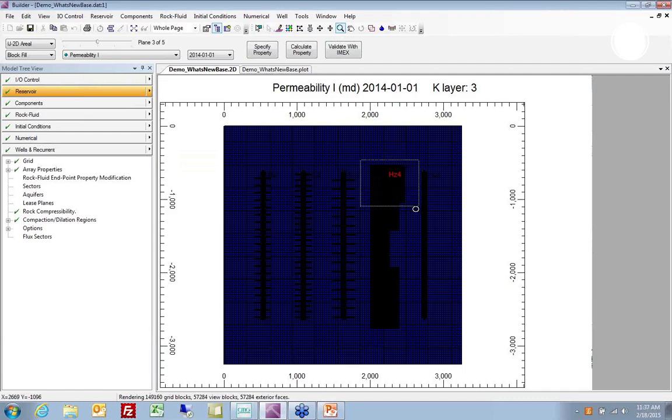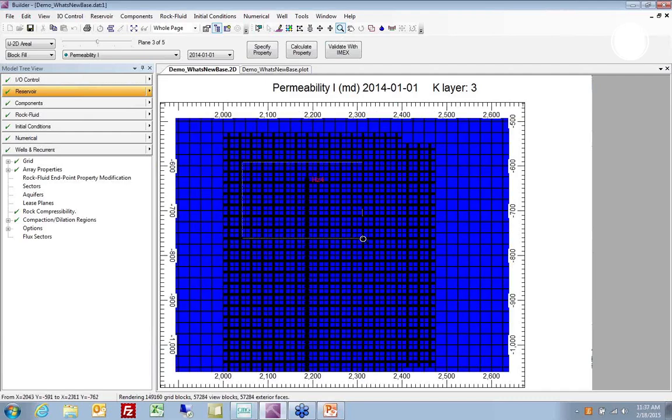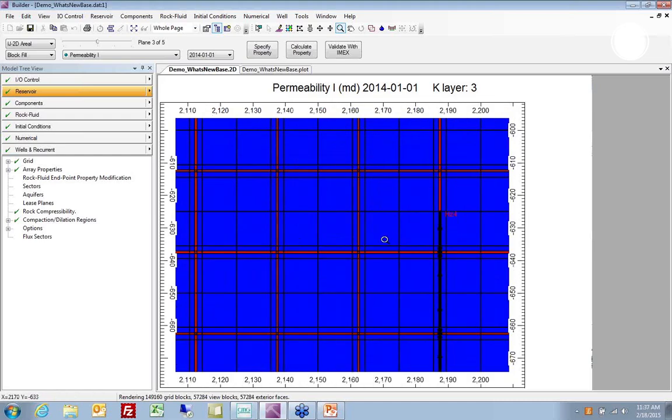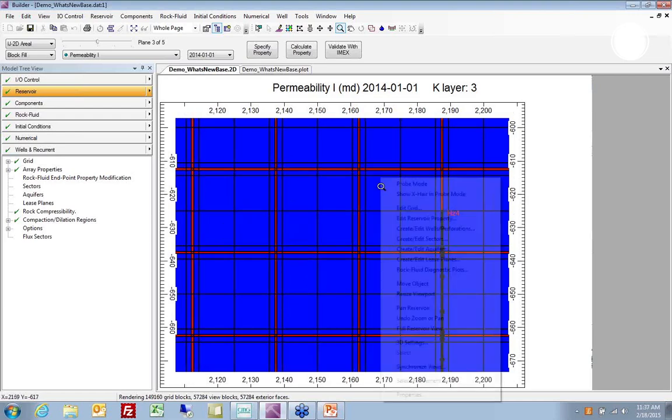So once again, I'll zoom in on the fracture and we can see what has been added to this network. In the dark red color, we can see my propped fractures within that stimulated reservoir volume. As well, we can see the local grid refinement added around each of these different fracture elements with logarithmic spacing, giving us different permeabilities as we go away from the fractures.